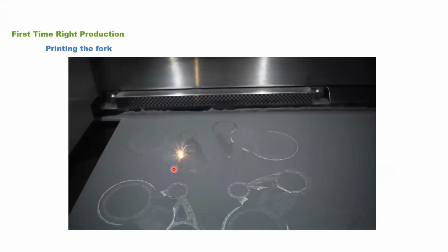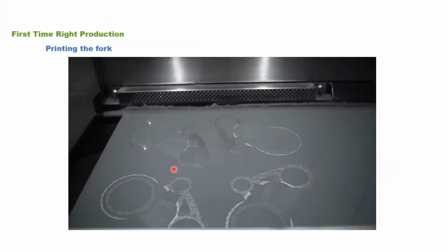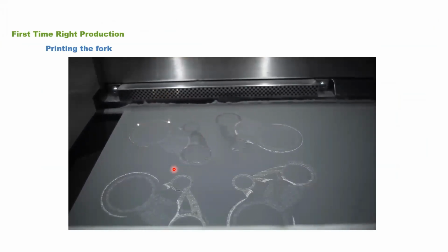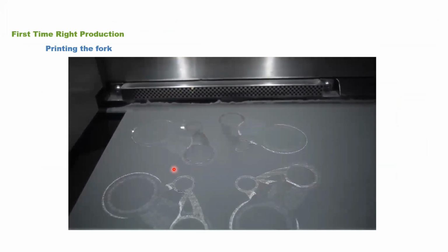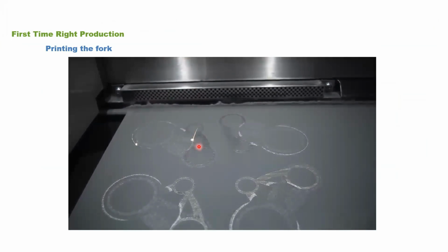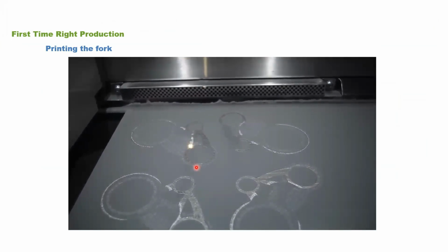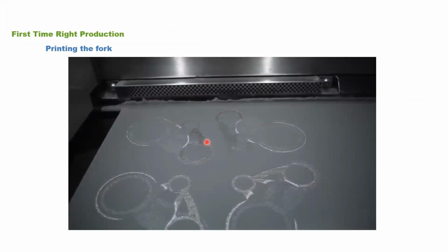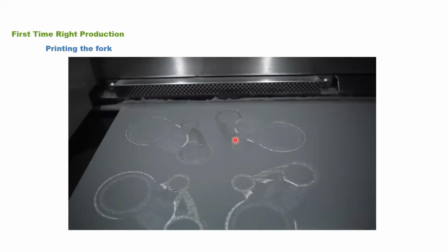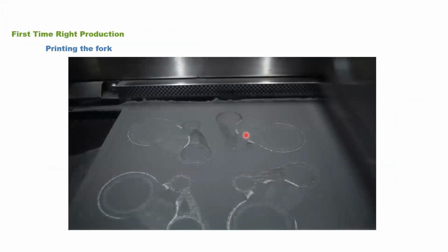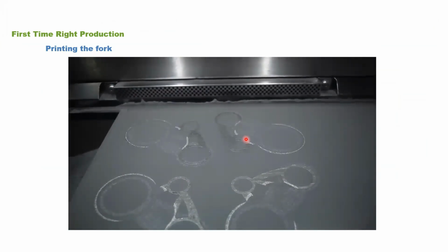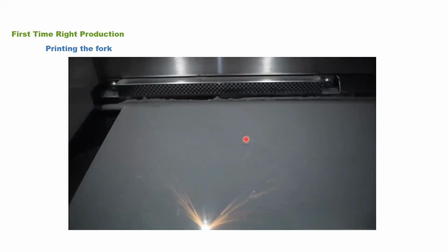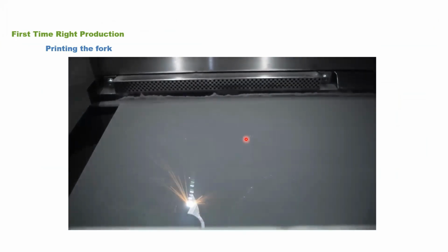Okay, so this is the powder bed on which the material will be laid, and these are the lasers that are coming onto the part. So you can see slicing will be done, where each part will be manufactured layer by layer. Once this particular melting is done, these areas are getting melted. You can see the recoater going in, and the powder getting laid again. Then another layer is manufactured.